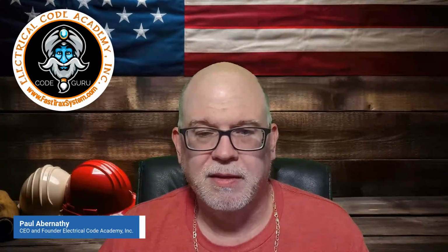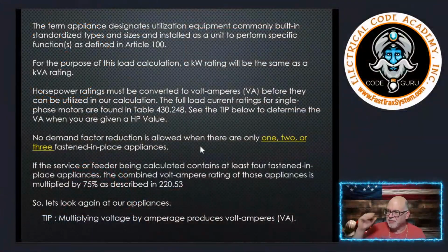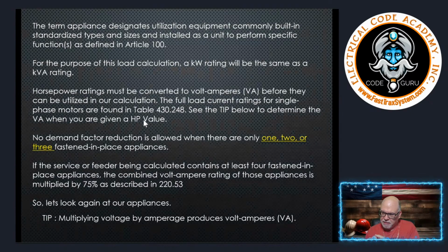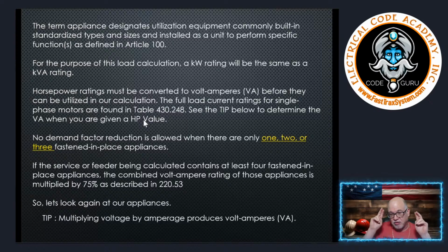All right. So let's go look and see what we got. Okay, now the first thing that we also want to remember is that typically in residential calculations like this, anything with a HP or horsepower rating is a motor. But a trash compactor, dishwasher, things like that, we don't consider those as motors.